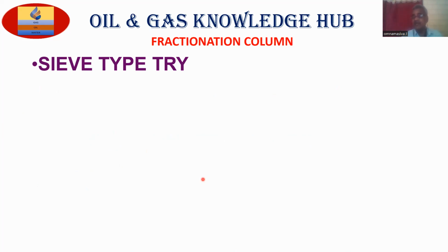The shell material would be alloy steel or P9, some high corrosion resistance material they will select, as per the ASME Section II materials. And any internals, maybe trays, maybe support girders, any steel structure inside the process column.